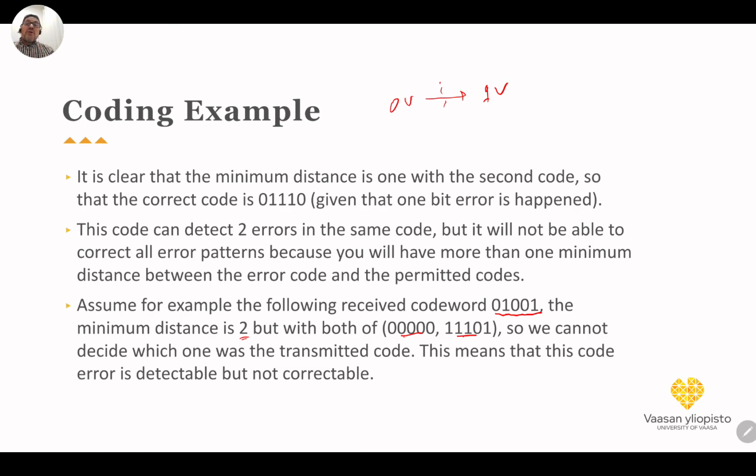However, we can improve the decoding process by using a soft decoder. In the soft decoder, we keep every signal, for example normalized from 0 to 1, as it was received. For example, we don't receive 01001, but assume that we receive 0.1, 0.9, 0.4, 0.01 and 0.7, instead of 01001.